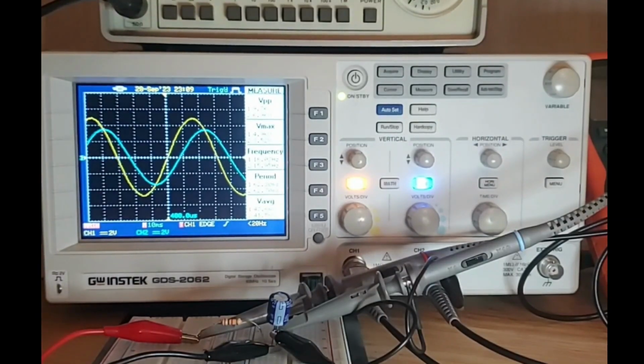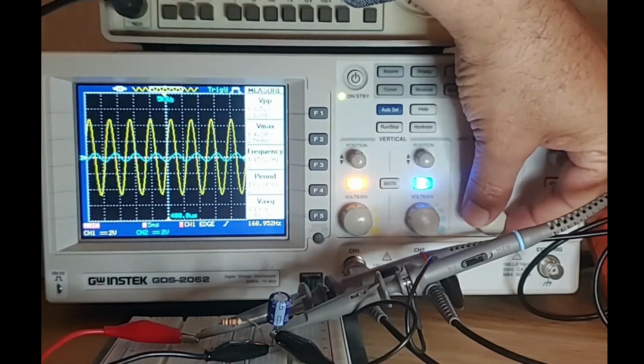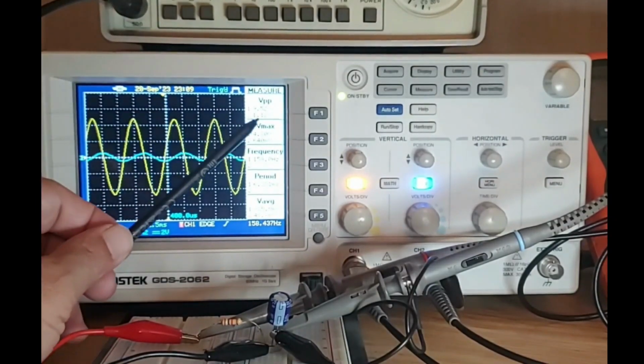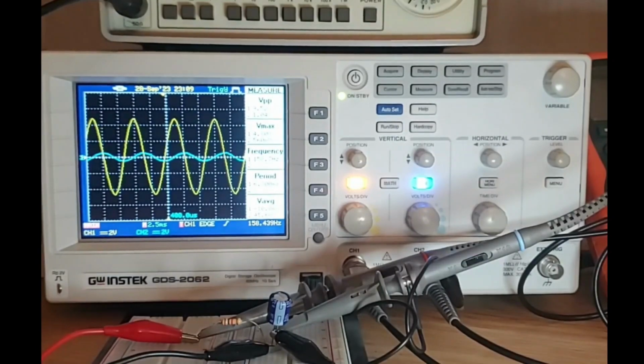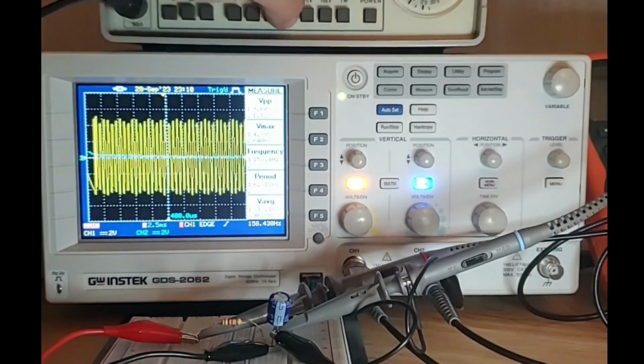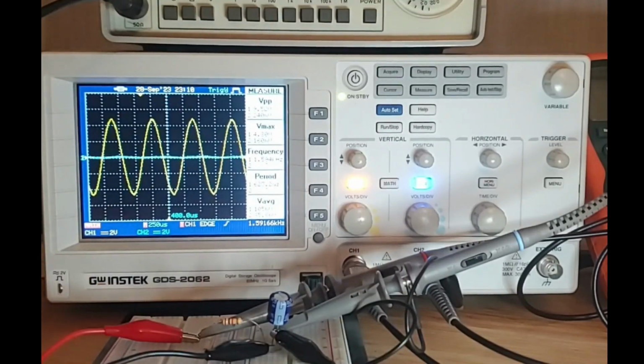Now, if I increase the frequency, from 16 hertz I can go to 160 hertz. And this is what we will see on 160 hertz. And now let's zoom in along the time axis. So you see that the capacitor voltage has decreased a lot. Now the capacitor voltage is only 1 volt. And the reason is that when I increase the frequency, the time period is much smaller now. So the capacitor doesn't have enough time to actually charge and discharge. If I further increase, the capacitor voltage is almost 0 now. And the frequency is 1.5 kilohertz. So you can see that the capacitor voltage is almost 0.